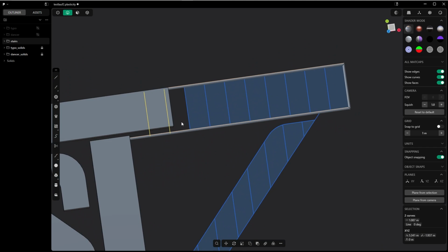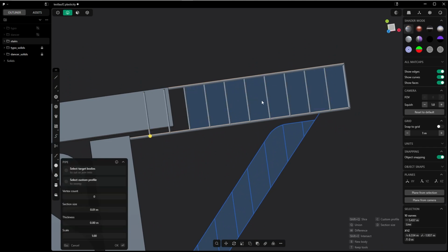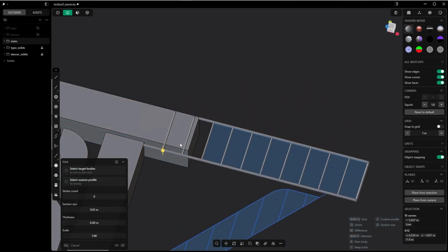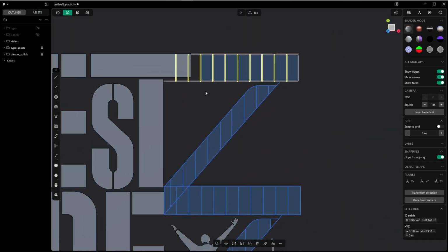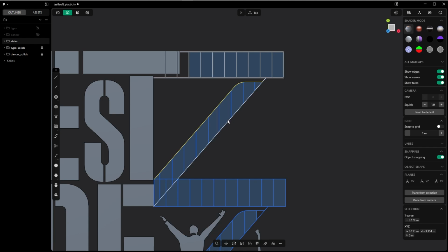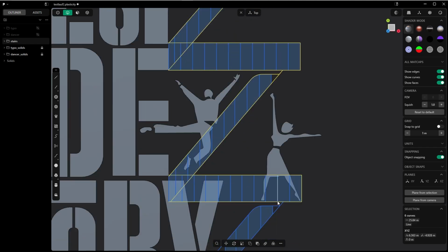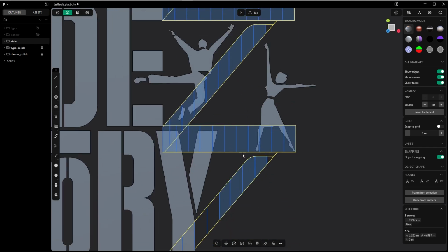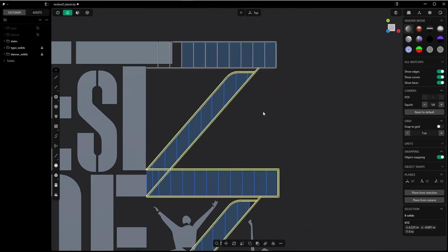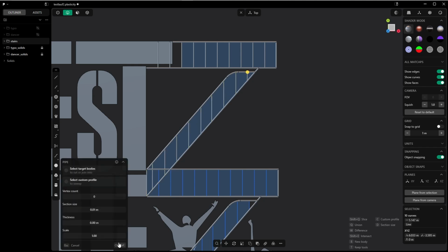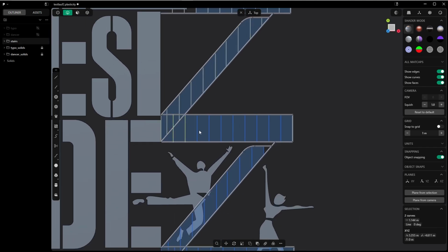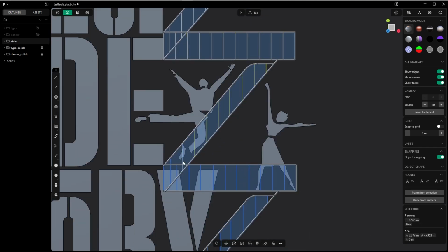So let's do the same with these, but these guys should be thinner. So let's pipe them, and 0.01 should do the job for these ones. And we can do the same for all the other guys. So these outer pipes should have the thickness of 0.015. And the small ones, the short ones, 0.01. So you can just press P and confirm. And we won't do any fancy filleting or boolean or whatnot. We will leave it simple.